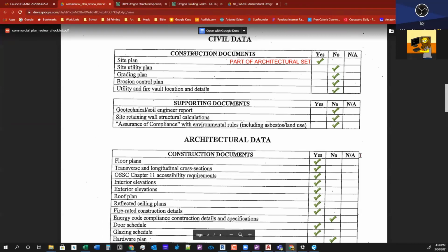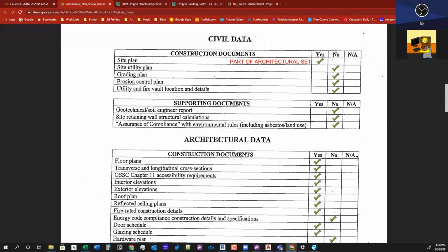So like at the campus, it's really swampy, kind of wetlands kind of stuff. I worked on a project over there, that Sedici's Pizza over by the campus, with a lady who used to work at an architect office that I worked at. She went on her own and she designed that Sedici's Pizza. Well, that site, the ground was not great for putting a building on. So they had to put really deep cylindrical concrete piers in the ground to support the building. So there would be really deep concrete piers with concrete footings on top of them, and then the building would be supported by that.